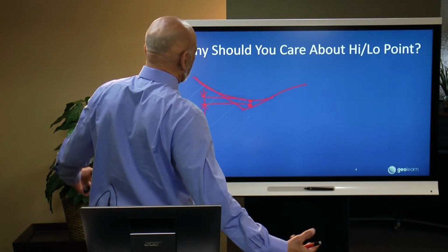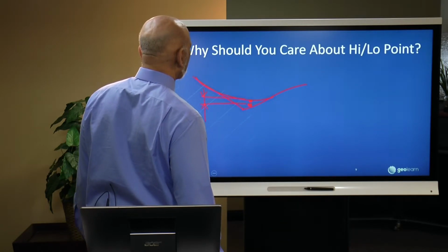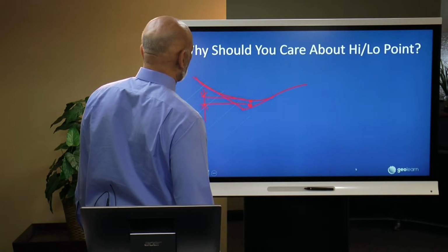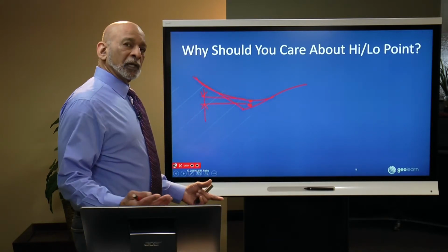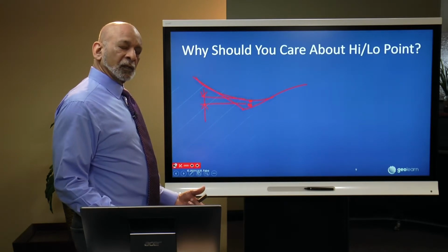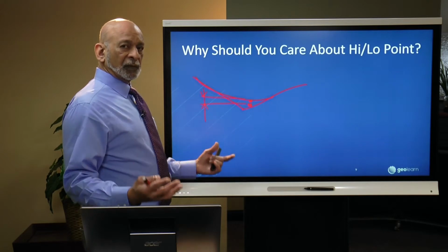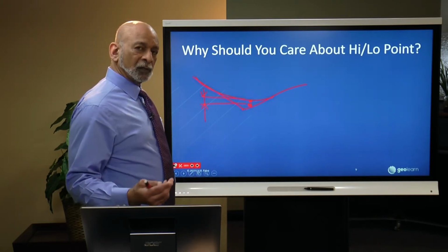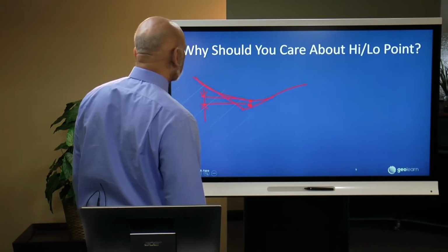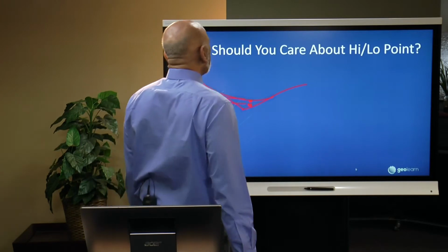And then from a surveying point of view, the surveyor may have to come in and actually provide control, vertical control, to enable the contractor long before the road is built to make sure that the pipe is located in the right place, and also that it's sloping in the right direction and with the correct amount of slope to make sure that the water flows through from right to left or left to right, depending on which way the water is going to get taken away.